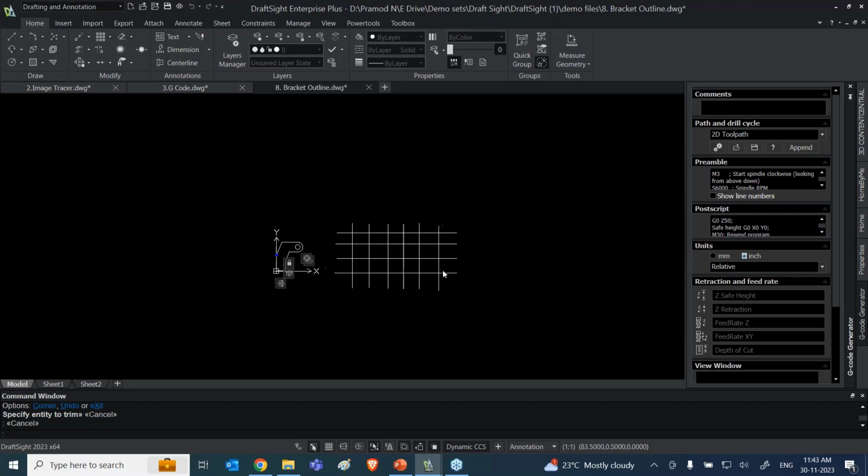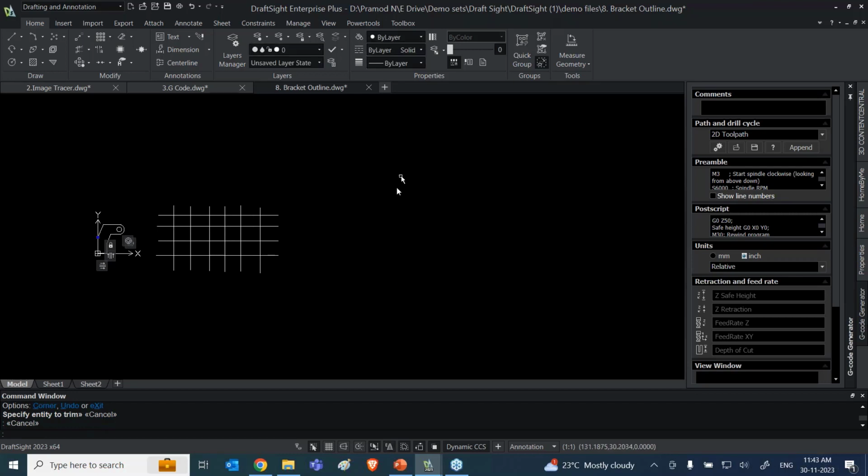So next, what other extra features are available in DraftSight? Just by right clicking on my mouse and moving my cursor, I have a shortcut bar that has been activated over here. This we call mouse gestures. Frequently used commands can be arranged over here so that the designer need not select the commands from the ribbons or type them on the keyboard.